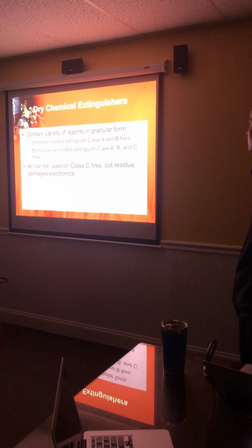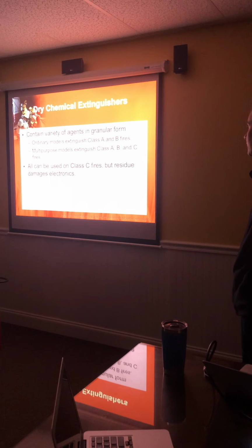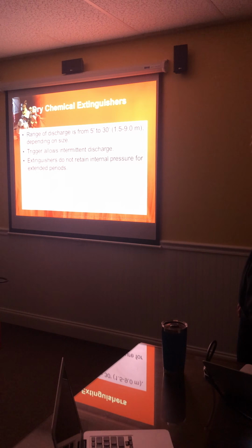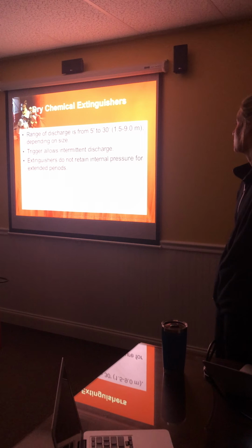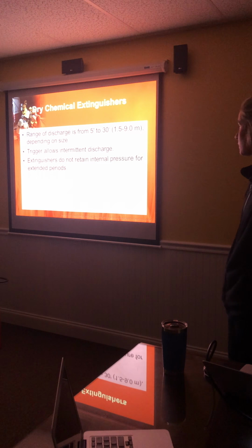Dry chemical extinguishers contain a variety of agents in granular form. Can also be used on Class C fires, but residue damages electronics. The range of discharge for the dry chemical extinguishers is 5 to 30 feet, depending on the size. And the trigger does allow intermittent discharge.